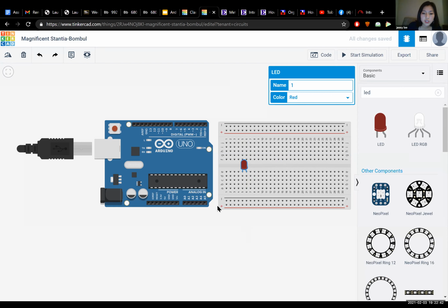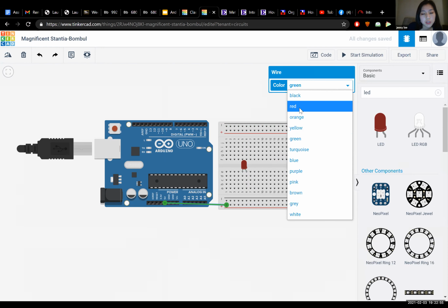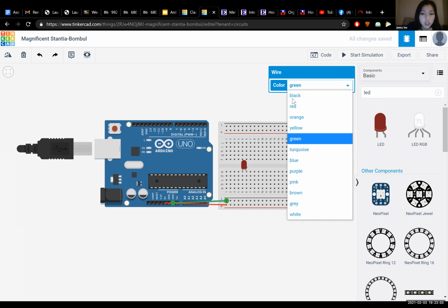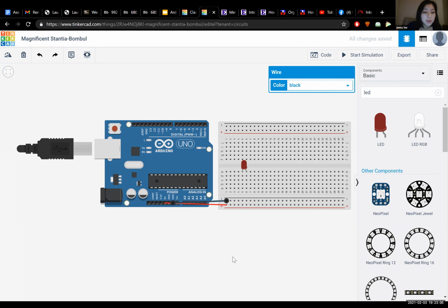So first let's give power to this place. So connect the 5V pin to here. And usually conventionally when we're making a circuit, power is always red. So I'm just going to do it. It makes it easier on the eyes. And then let's connect ground to here. And then conventionally ground is always black. Ta-da. So now basically we provided power to every single pin here. So if we want power, we could just connect it to any pin here and it's going to give power.